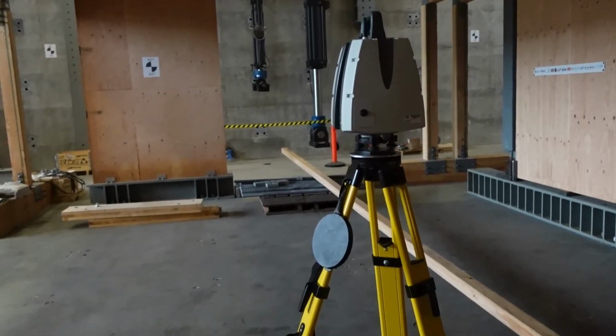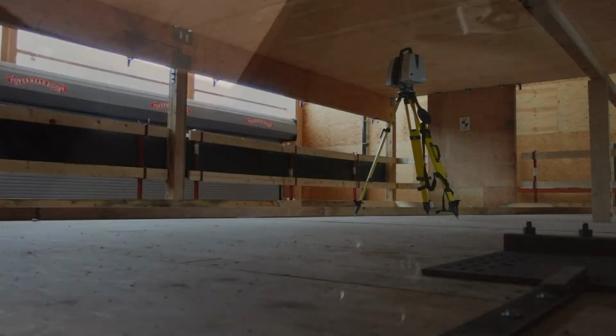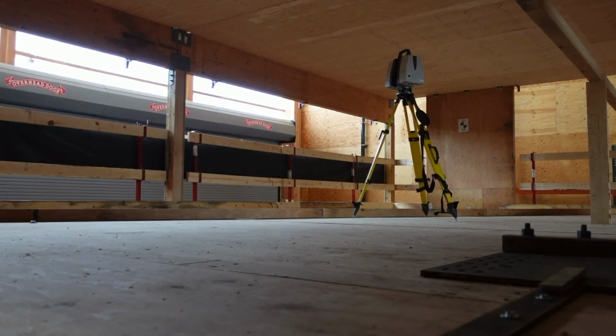What you just saw was the input for the Leica P50 laser scan. This device has a longer distance range with high resolution compared to the RTC360, so it was very useful to capture the outside faces of the building. Nevertheless, the time for each scan with pictures included was around 15 minutes, so we only used it in fewer locations in the building.